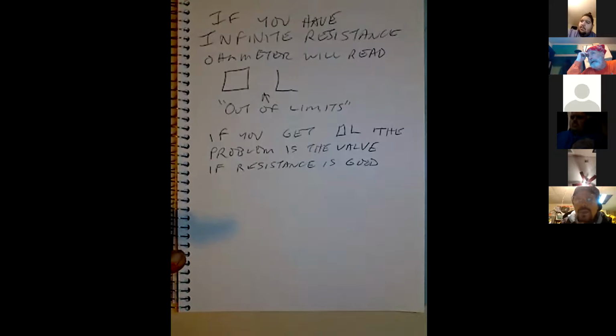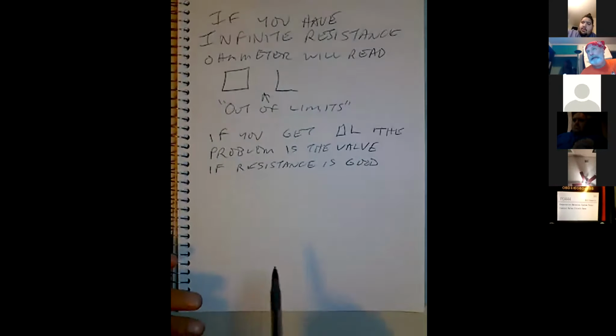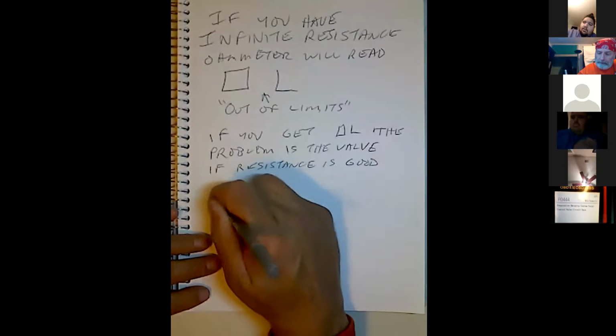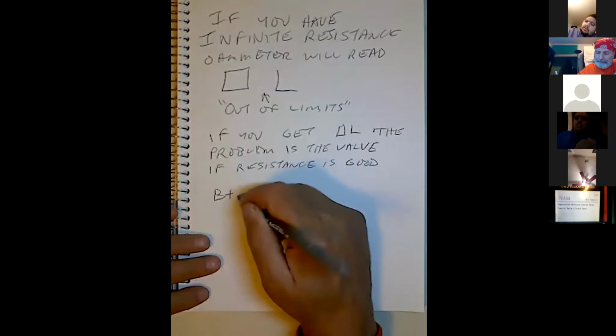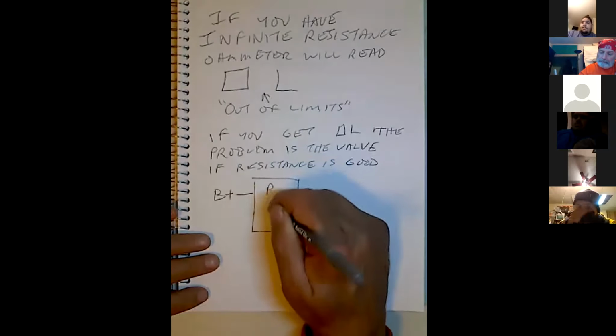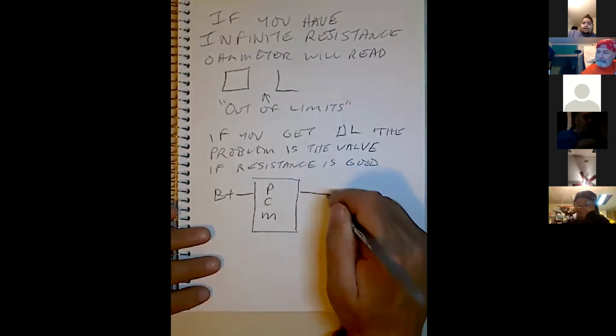Yeah, I got a 441 and a 444. What's a 444? A 444 is evaporative emission system purge control valve circuit open. Yeah. Well, that's a bigger problem. I hate to tell you, but that's a bigger problem. It is? Yeah. Got a B+ here going into the computer, the PCM. Tony, that also could be a dirty ground too.